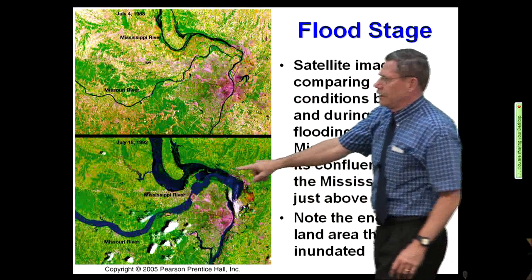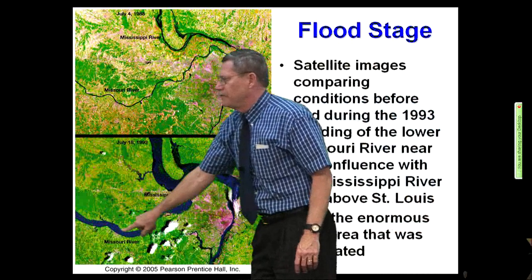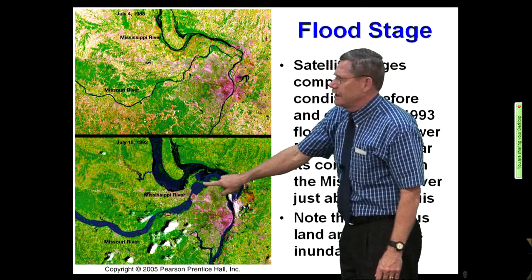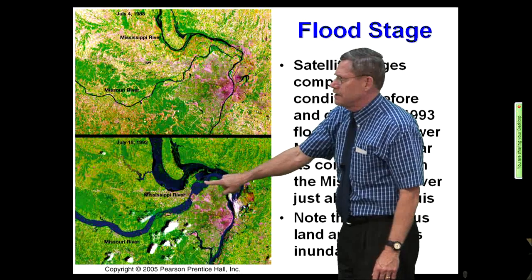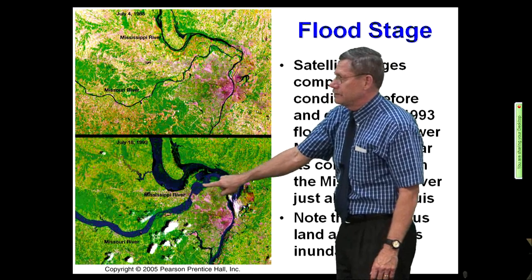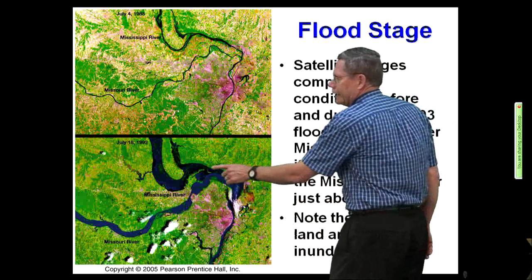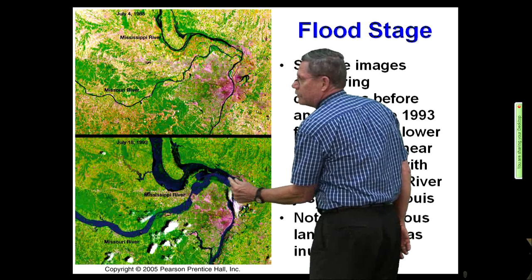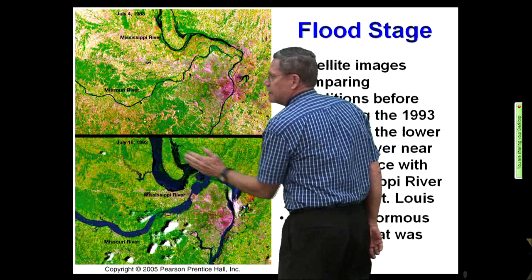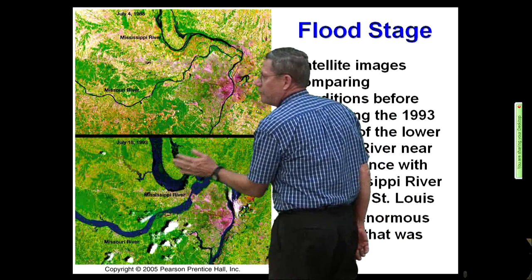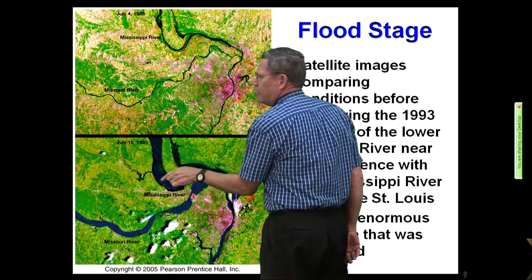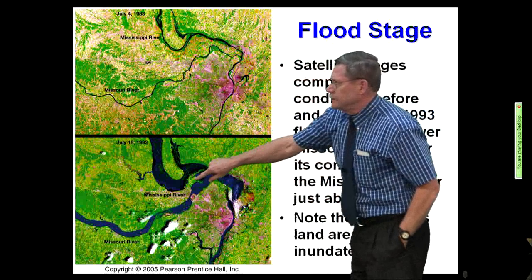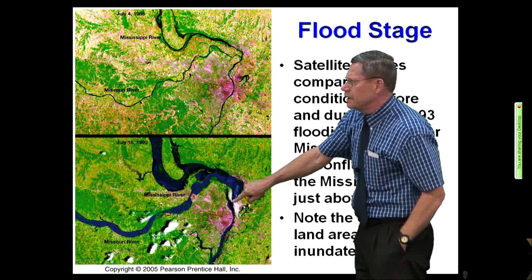And what's going on here is you have the Missouri River in full flood that entire summer, late spring and summer. And then you get down to places like this, near St. Peters and St. Charles, and you got dikes protecting the development. St. Charles predates St. Louis. And so you got dikes here, you're narrowing the water, and so as you join this other river here, you have a backwater effect. And that's what you see damming these other things up. They're backwatering and washing out all the Army Corps of Engineers locks and dams, going upstream here for quite a ways. So this system comes around, and then it hits the improvements around St.